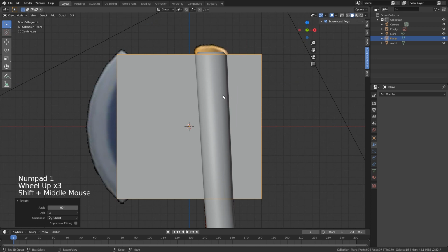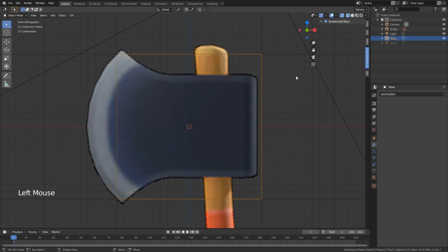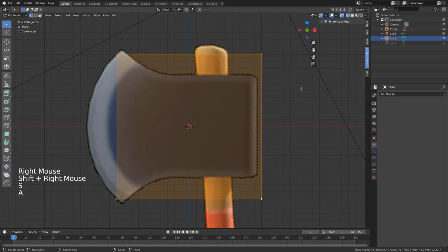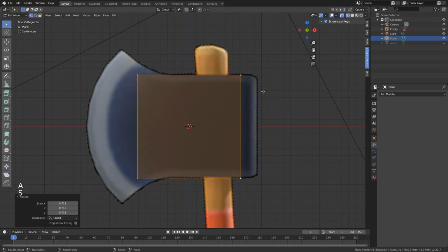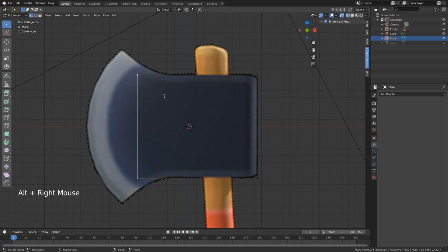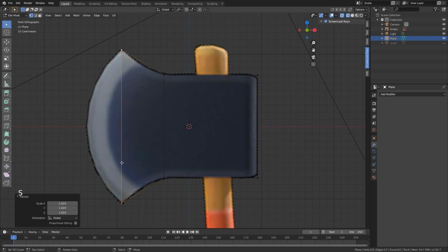And if you go into the front view, we can see that we barely can see our X behind here, right? But if you go into here, you can change your viewport shading to wireframe. And now you can look through your model. So the only thing I want to do now is scale this a little bit down. I'm gonna move these two here to the right, and this I'm gonna move to where the X starts to kind of separate, let's say. Now I'm gonna extrude again, and I'm just gonna scale this up until we reach these sharp edges.